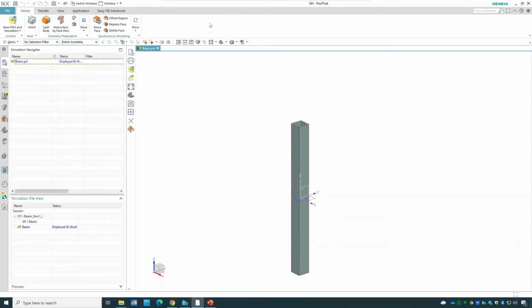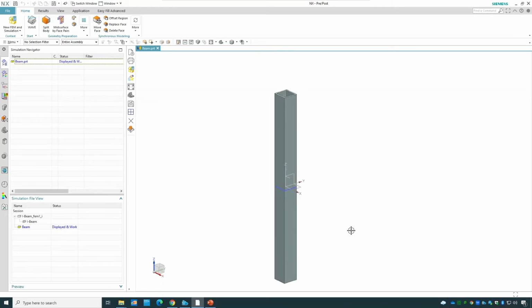And in here, you can see I have an option for a split body. The reason we're gonna use a split body, assume that this model has or needs lots of the computer power in order to do an analysis on it. And because this model is fully symmetrical, what I'm going to do, I'm gonna only study one part of it, half of it, and let the computer duplicate the result for both sides. This would enable me to save lots of time. It's the same thing for lots of the calculation as well. So this method we will use for symmetrical models, for instance.